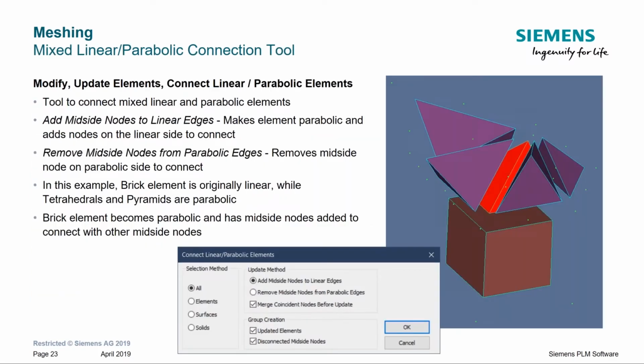Rather than what we were showing you before, which was the mesh solid tetrahedral command, you can also modify update elements and connect linear and parabolic elements with pyramids.